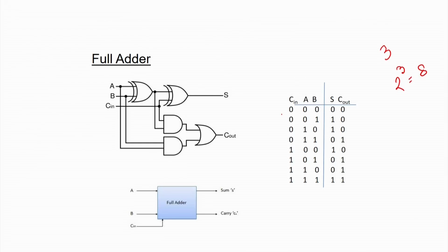So, we have listed all those possible combinations over here, and depending on the behavior of addition, we are going to find out what my output function will be. Now, once we have this particular output function, then we can implement it with the help of this particular circuit. This complete circuit will be treated as my full adder, and finally, once we give the signal over here, say 1 1 0, we are going to get the output as 1 and 1, sum is 0, carry is 1.